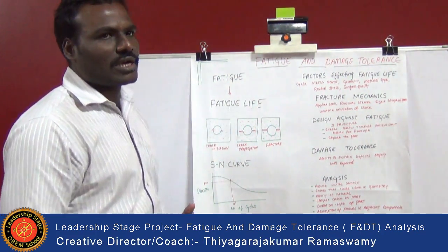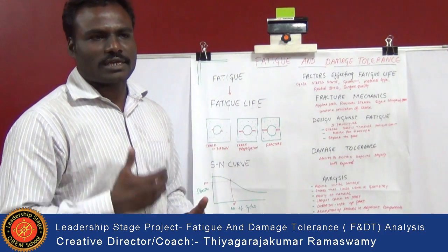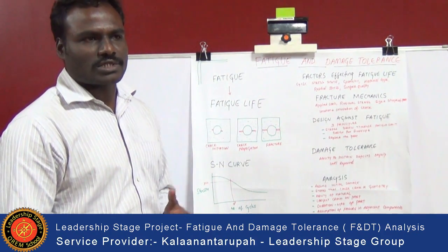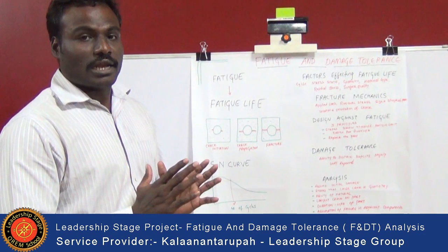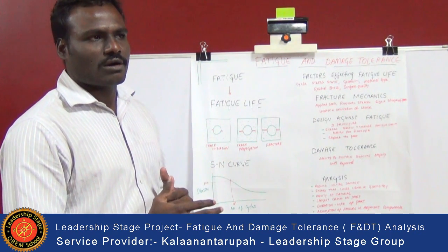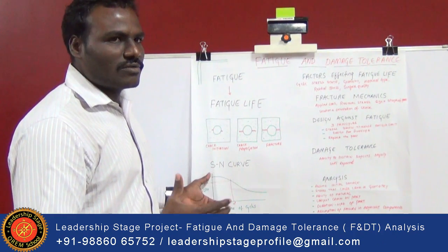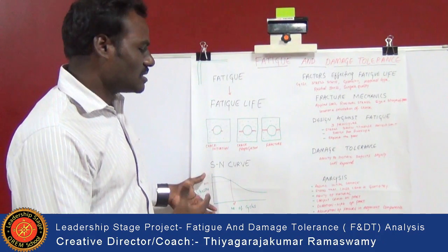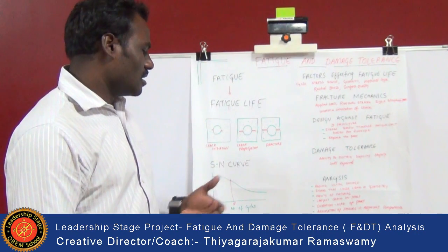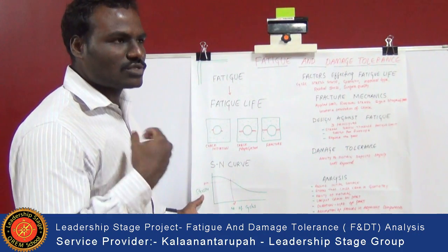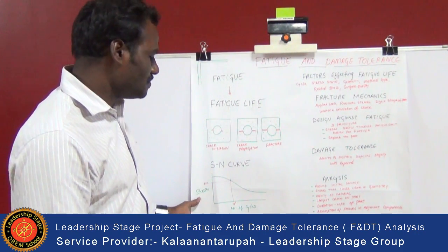For this purpose, we need to find out the fatigue strength of the material to sustain a life cycle of the material. For that, we need to develop an S-N curve with respect to the number of cycles and the actual stresses applied on this material.